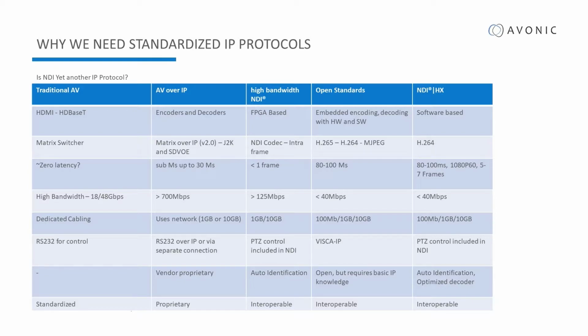Then how does NDI fit in? Within NDI, there's two flavors. They're both NDI, but let's start with the one that is closest to the AV over IP world, the SDVoE world. The high bandwidth NDI. Compared to the other two that I explained, it's FPGA based. There's still a piece of hardware in there, but it's a dedicated FPGA.